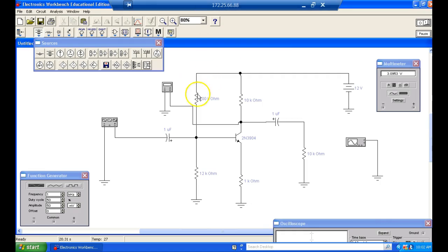Now, what could cause that to happen? Well, we could have more current over here, but when I come over here and look at this guy, it's sitting right where it's supposed to be too, right? You understand? Okay. So it's okay. This guy right here is low. So what does that mean? Well, it means the 10K either got bigger or there's more current flow through it, right? And of course, the problem here would be the 10K could be bigger, right? So we got two problems. The 10K could be bigger, so its resistance could have gone up, or the capacitor could be shorted.